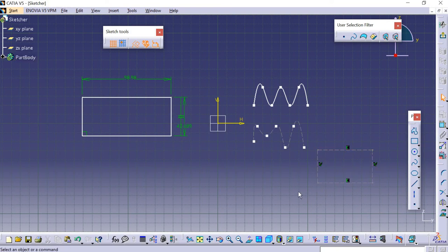Now orange is when we select an element or a subgroup of elements. Once we click the control button on the keyboard and click on this line and this line and this line and this, it turns orange. So it is called a selected element. And as you can see, the white rectangle is an under-constrained element, as the geometry has been constrained. That is, all the relevant dimensions are satisfied, but there are still some degrees of freedom remaining.